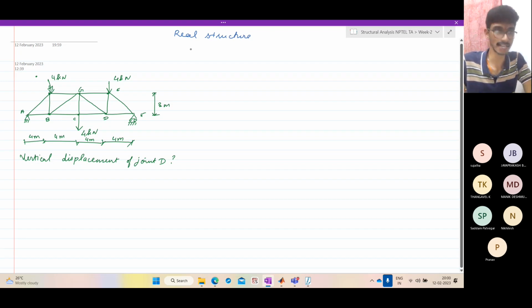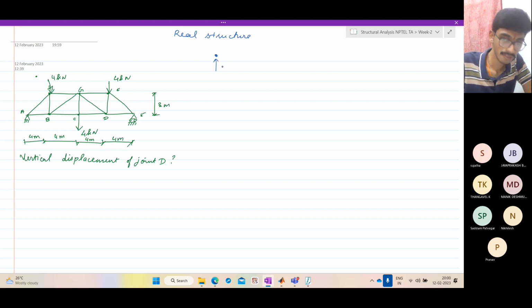This looks difficult, but it's actually simple. Okay, so again, as usual, it is symmetric and there are no vertical forces. So let us use the method of joints. Let us look at joint A. What is the vertical force? Quickly, 6 kilonewtons.